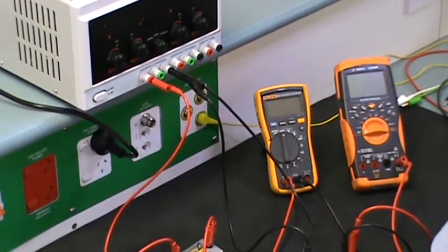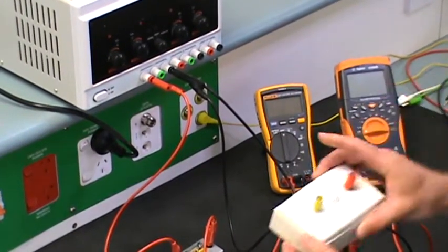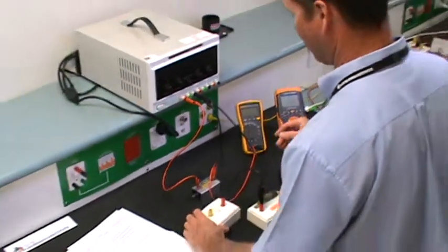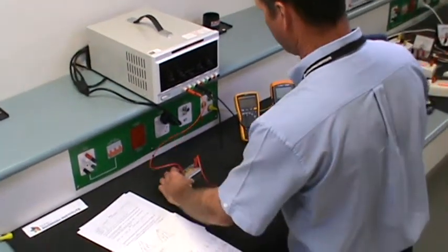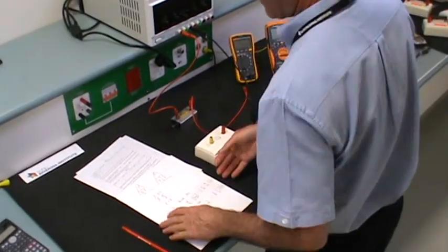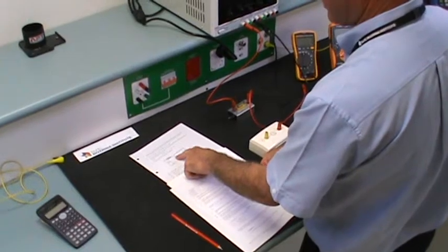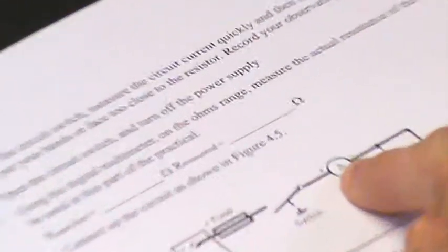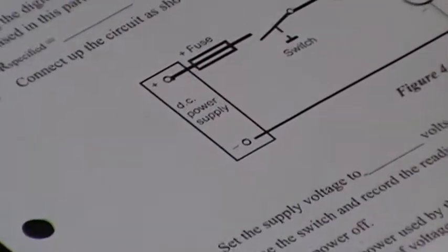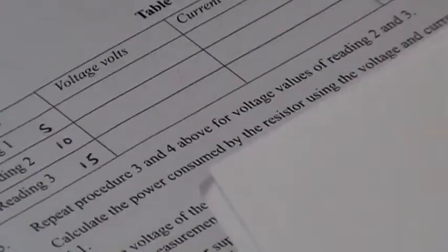One thing I haven't wired in, which we've forgotten, excellent, those that have picked it up, is the switch, probably most important. So we'll refer back to our circuit diagram there and see where we went wrong. You can see there's a switch. I've jumped from the fuse into the ammeter and forgot the switch. Probably a pretty important part, so let me put the switch back into play.